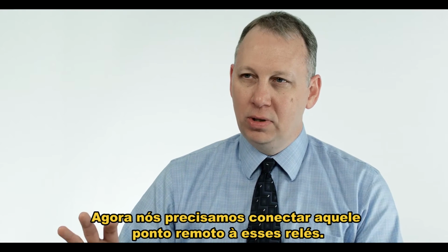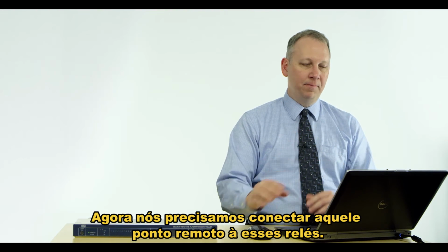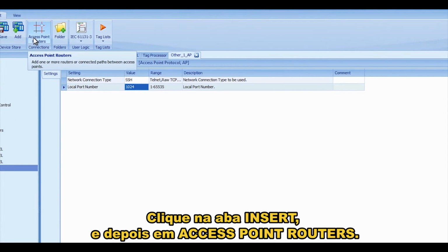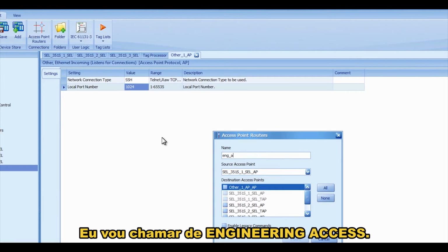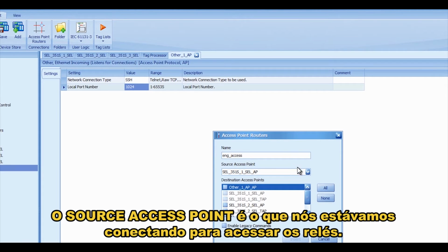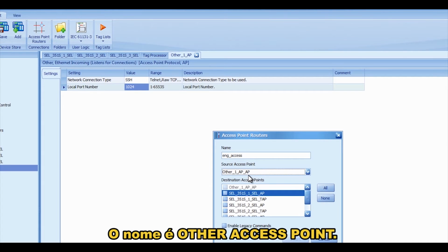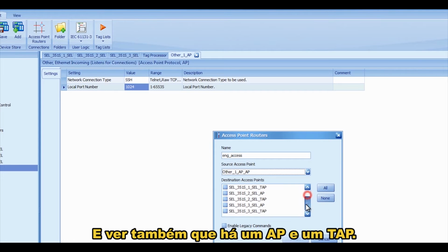So now we need to connect that remote point to these relays. To do that, we use the access point router. Again, from the Insert ribbon, click on access point router. You can change the name if you wish, and so I'm going to call it engineering access. The source point is the point that we're connecting to get to the relays, and that's the one that I just put in there. It's called Other Access Point.